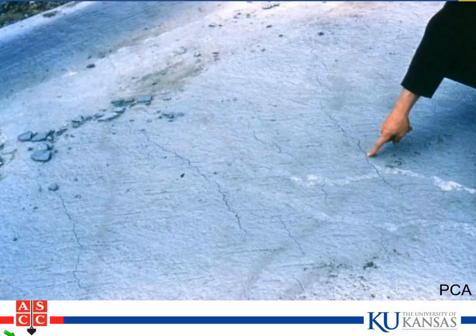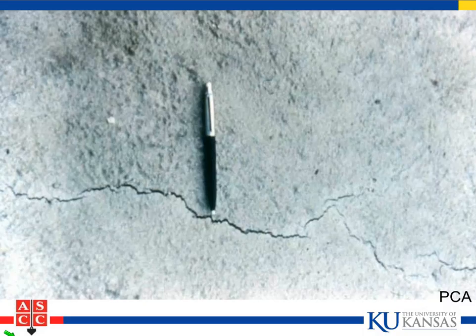If you just have 1 or 2, you can put a 2x4 and smack it with a mallet and close it up. But you cannot trowel over plastic shrinkage cracking. They will reflect up through whatever amount of cement paste that you've used to cover up the crack. So and here's another example of a plastic shrinkage crack.